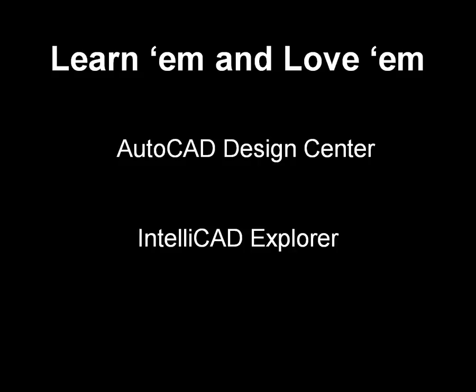But if you're a CAD manager, you know what happens. Every time someone purges and has to manually change that or create that layer again, they may remember the color and they may not. They may actually give it a good attempt, but they may not. And really the philosophy you need to use, particularly as a CAD manager, is it needs to be easier to use a standard than it is not to use the standard. So we have tools like AutoCAD Design Center and IntelliCAD Explorer that will allow us to recreate those standard elements.